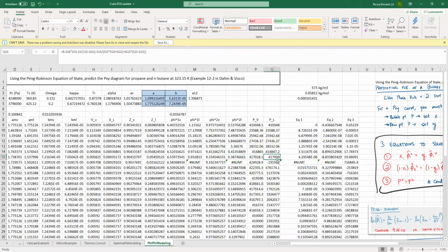All right, so all I need to do here is double check, why am I getting a negative number? And that is because I've got a molar volume for the liquid that is out of line from expectation. So if I just copy that value down, it should go back positive, and it shouldn't give me a number error anymore. Again, that's not going to fix the problem. I'm just trying to work through and troubleshoot all the things that it could be.